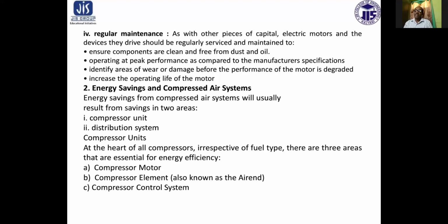Reducing the compressor inlet air temperature by shading the location or by increasing the ventilation of the inlet can also offer significant savings. The correct installation and commissioning of new equipment, as well as regular recommissioning of existing equipment after major service and repairs, should ensure that the system is operating efficiently.